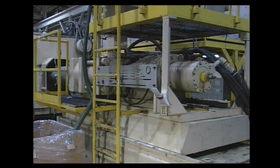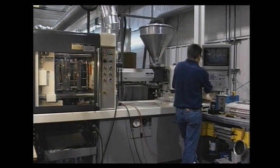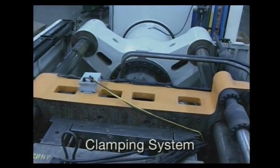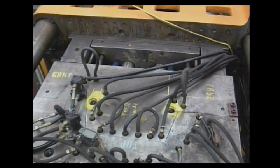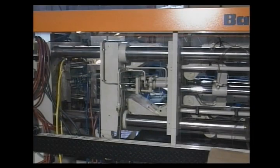There are two types of injection mechanisms: the reciprocating screw, which is the most common, and the two-stage screw. The function of an injection molding machine's clamping system is to keep the plastic material from leaking out or flashing at the parting line of the mold's cavity and core. The clamping system has two configurations: a fully hydraulic system and a toggle system.